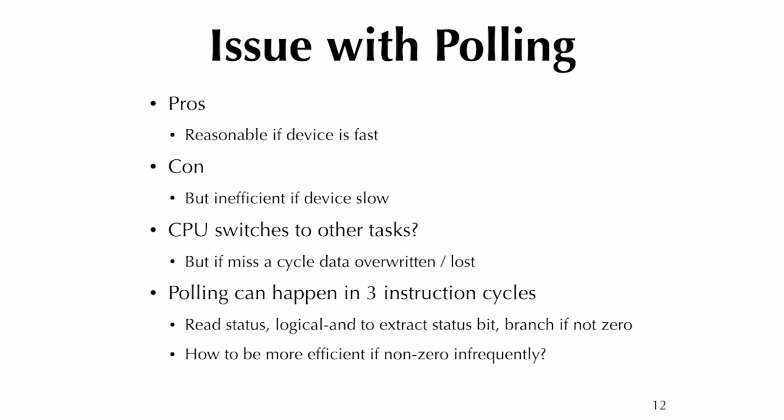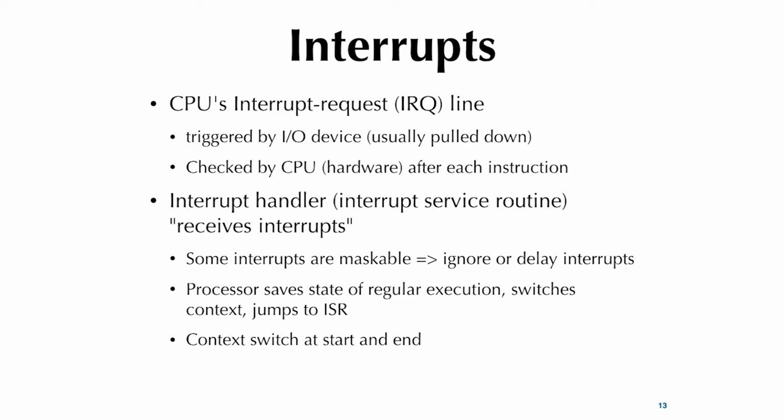Whereas an interrupt notifies you much more quickly. So that's why interrupt could be much better in terms of serving that and not missing out on events. Of course, the premise is that your interrupt service routine shouldn't take too long. Otherwise, it would have the same issue.